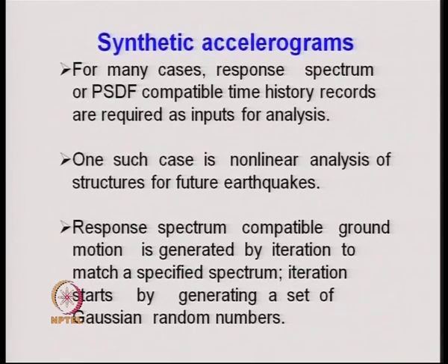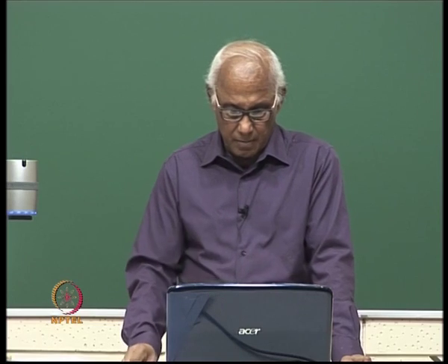And these compatible time history records are many a time required for performing nonlinear analysis of structures for a specified response spectrum or a specified power spectral density function. And as all of us know, the response spectrum method of analysis and power spectral density function method of analysis are valid for the linear case. Therefore, if one has to perform a nonlinear analysis, then one has to obtain the compatible time history records.